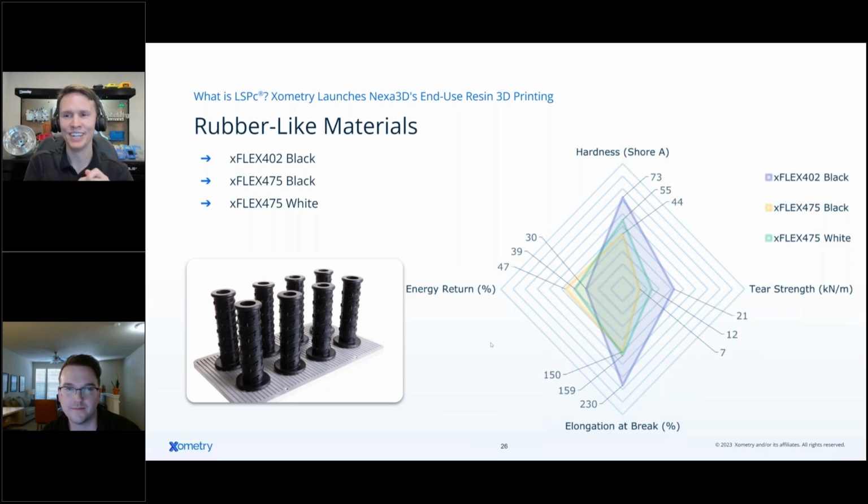Essentially, it's how much does it stretch, and then it'll tear on you. Where these materials are much more robust, they have elongations from 150 to 230%, and the energy return is really important. And I think that's a marvel in photo resins that I've seen recently, a much more responsive material. So that's when we're seeing those grips, those insoles, those paddings being created with these processes.